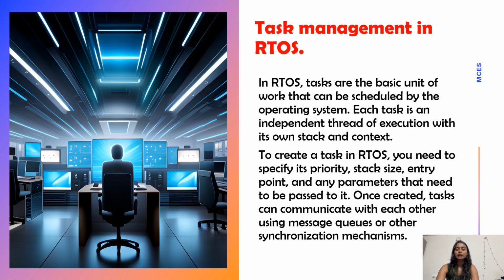Task management in RTOS. In RTOS, tasks are the basic unit of work that can be scheduled by the operating system. Each task is an independent thread of execution with its own stack and context. To create a task in RTOS, you need to specify its priority, stack size, entry point, and any parameters that need to be passed to it. Once created, tasks can communicate with each other using message queues or other synchronization mechanisms.